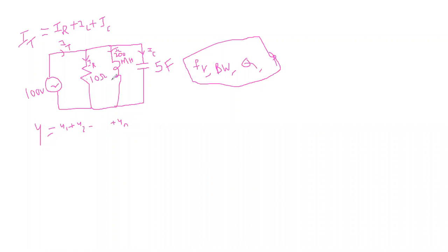Here, this is admittance. That we are considering, this is resistance. Admittance means the reciprocal of resistance is the admittance. Then here Y is equal to G plus jB form, as in the last class. G is the conductance, B is the susceptance. Then here Y equals, from the circuit, the reciprocal of all the parameters.